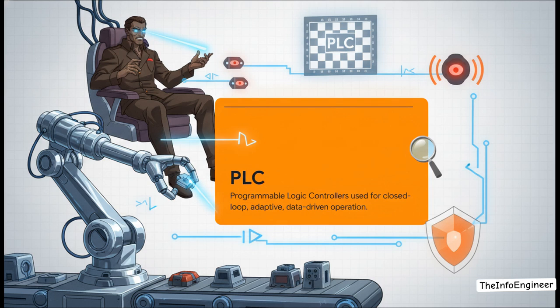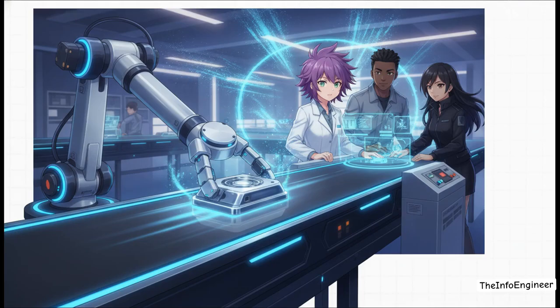The PLC reads inputs from hundreds of sensors, executes the logic, and perfectly times the handoff between a moving conveyor and our mathematically precise robot arm, making sure production is fluid and continuous. So, since you're managing these projects, here is a massive pro tip for process optimization. The secret to high factory output is not just going out and buying a faster robot. It's using the PLC to eliminate the arm's dwell time, that's its idle time, through perfect synchronization.